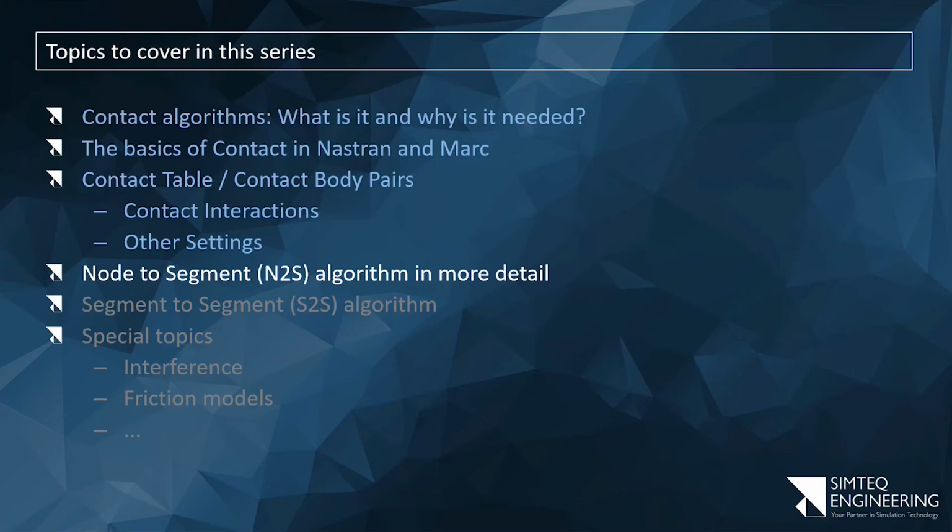So a little bit of strain will also always be visible and so on because there's an elastic modulus. It may move very little or have very low strain before it fails, but there is still a strain. So you can define that, for argument's sake, as a 1e minus 6 strain or something weird. Okay, so you still have to go back to stress and then, okay, understood.